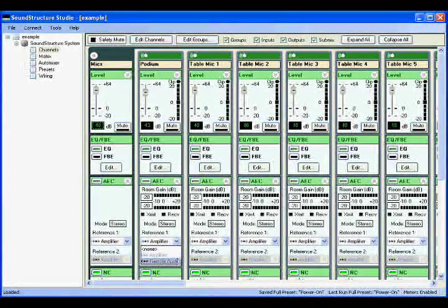With this change, the echo canceller reference for the podium microphone includes all the remote audio. The echo canceller reference for the table microphones can be left as the amplifier channel. This way, when the podium microphone is active and coming out of the loudspeakers in the room, the echo canceller for the local table microphones will cancel any of the podium audio that might be picked up by the table microphones from the local loudspeakers. This will minimize any alternate path that the podium microphone may take as it's sent to the remote side, resulting in the highest quality presentation audio that can be heard at the remote site.